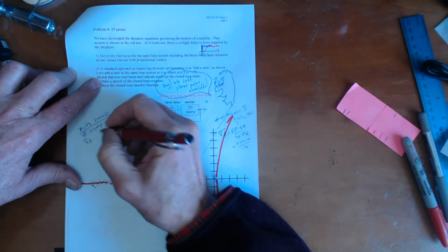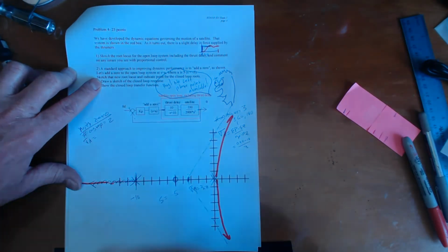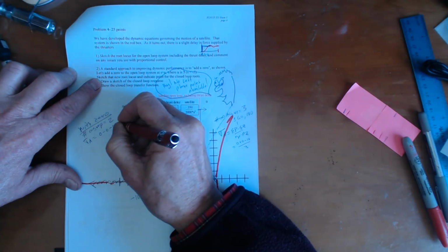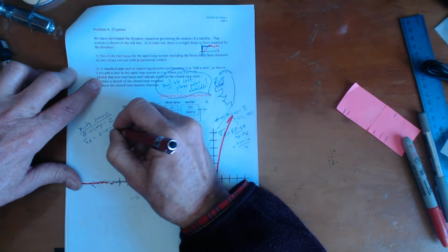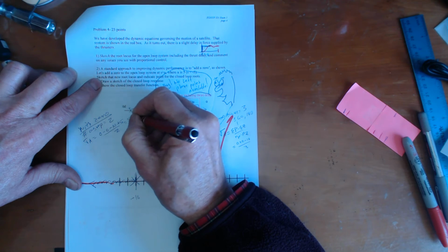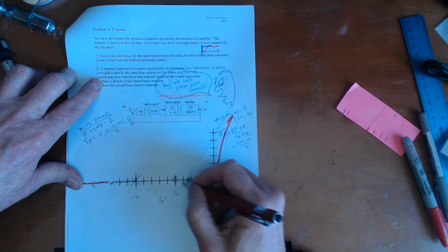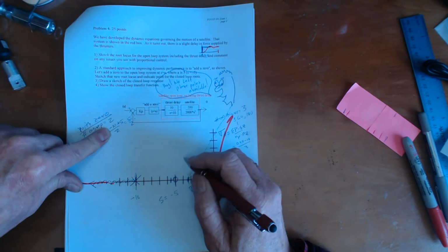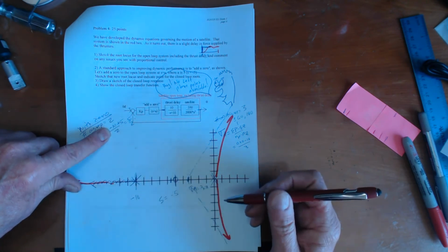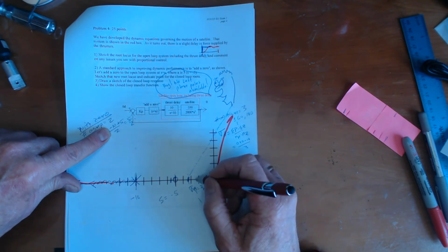The asymptote intercept point is equal to the sum of poles minus the sum of the zeros, so that's 0 plus 0 minus 10, plus 5, over 2, which is 5 halves. Here's sigma A for this one. Can somebody help me, what is 5 over 2? 5 over 2 is 2.5.